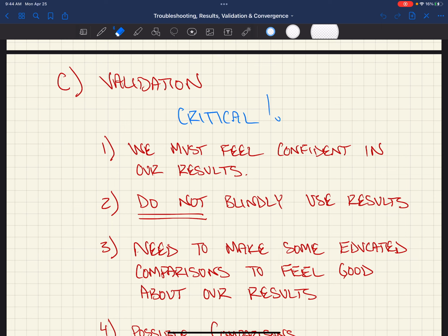Or someone else was working in the model and they like to use kips and inches and you like to use kips and feet, right? Or kips and pounds and feet. And so then they went in the model, they were looking at something, they changed the units, saved that model, and then you went out to go design some other member in there, and it's at inches and pounds, okay?